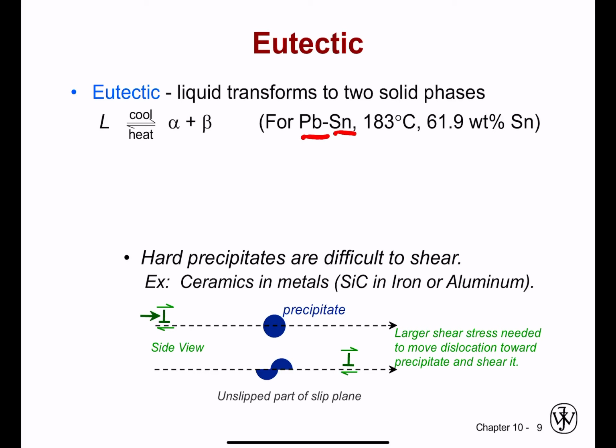And we're going to see that the eutectic point, that is where the single phase field liquid will transform straight into two solid phases, happens at a eutectic point as defined by the coordinates of 183 degrees C on the vertical and a concentration of tin on the x-axis of 61.9. Okay, so at those coordinates, we have an equilibrium between what's at right and what's at left. So right at the eutectic point, the liquid is in balance with forming alpha solid and beta solid.